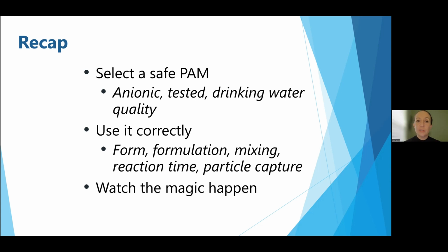You also want to make sure we're using it correctly. So we're using the right form. What type of application or treatment are we doing? What are our goals? Do we need a flock log? Do we need the silt stop? Are we doing erosion control? So we want to use the right form for the correct application. We want to use the right formulation. It must be matched to our specific site and water.